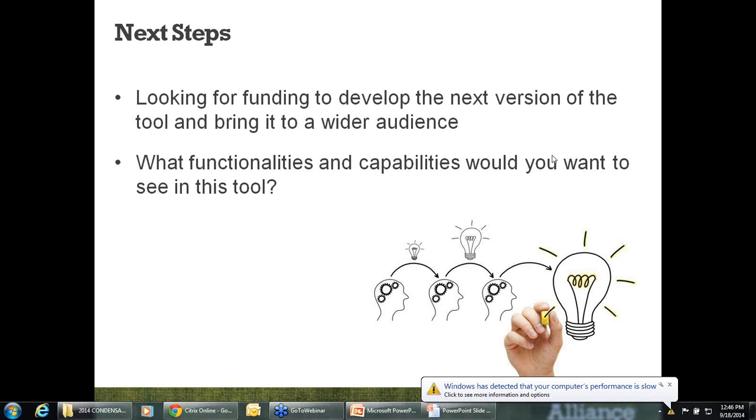I also have architects that I'll work with on a commercial level to some degree. I've had people run WUFI. Unfortunately, it wasn't the paid version. It was an unpaid, free version on the web, and an architect paid another architect to run it, and then saw this little blue line with a kind of moisture potential in the wall, and we had 3 inches of closed cell foam in the wall, and they wanted to put a poly vapor screen over the closed cell and then put the drywall on it. They thought that I was trying to sell them something, but I actually tried to keep them from having a potential problem, and I showed them the tool, and they understood that the vapor screen was unnecessary and actually would pose a potential problem.